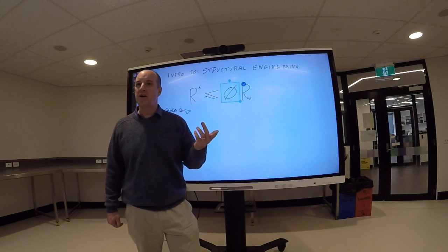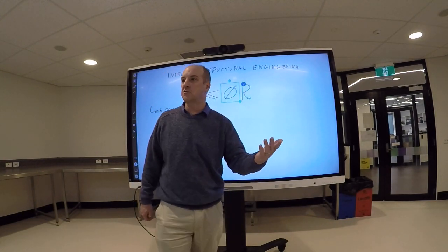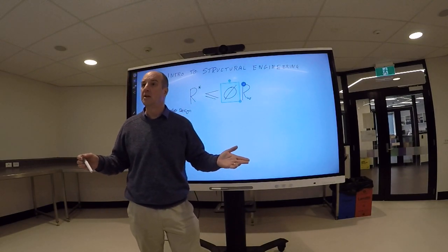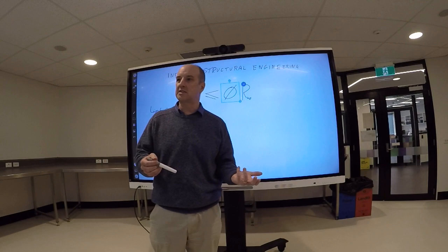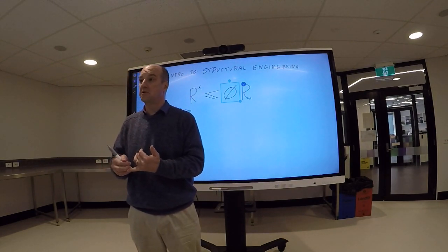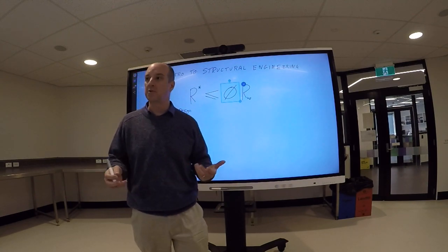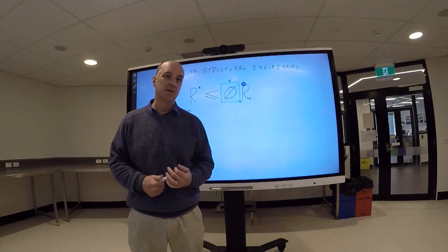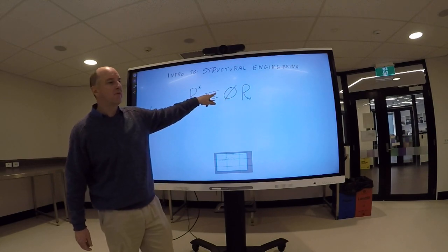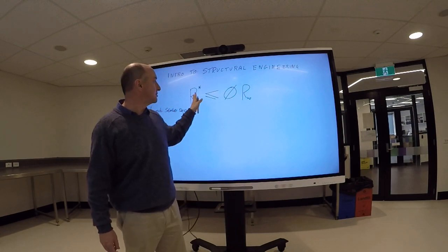Timber varies from 0.9 down to about 0.7. Concrete varies from about 0.8 to 0.6, depending on the situation. And the reason that concrete is less is because concrete is a less homogeneous material than steel. You know less about it. It's subject to all sorts of changes when you're making it, when you're casting it, all that natural variation. Now the phi factor I said for timber, there's more that goes into timber here, which gives us more conservatism. But that's basically what's happening there.